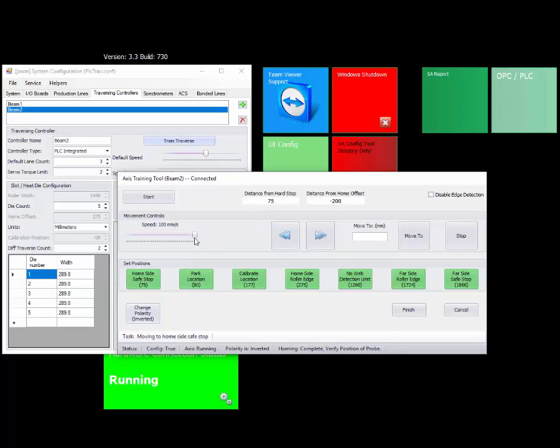What we need to do now is we can set our adjustment speed based upon how fast we need to move or adjust this speed. If we wanted to make sure we can move quickly, we can set it up to 100 millimeters per second, or down to say 10 millimeters per second at the slowest. And that would allow you to slowly move the probe across if you're really trying to get some sort of pinpoint alignment or be careful around some particular materials. Using the jog right and holding it, or jog left and holding it, allows you to move the probe in either direction and zone in on a particular position.